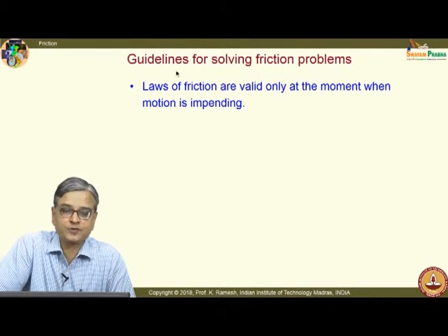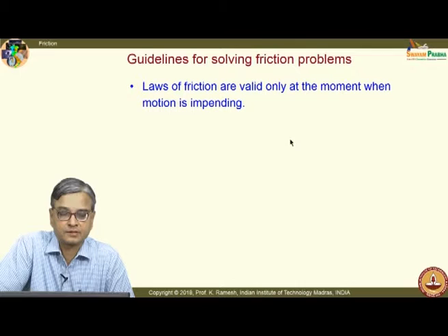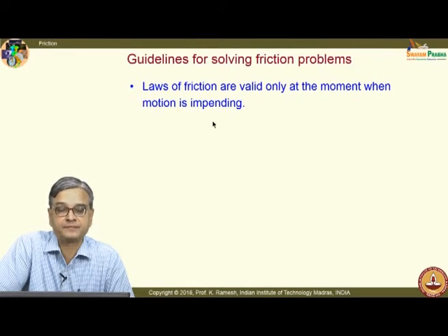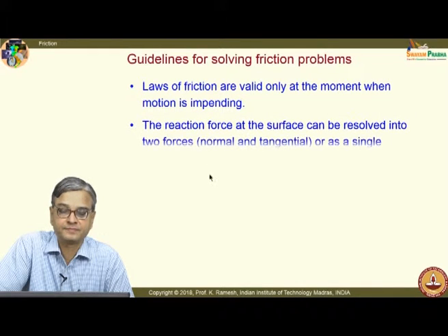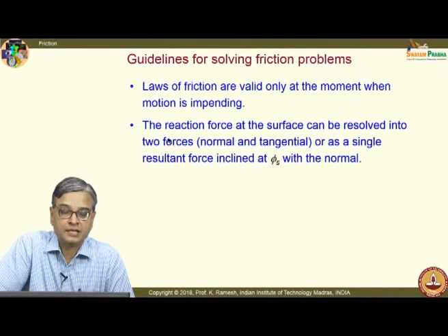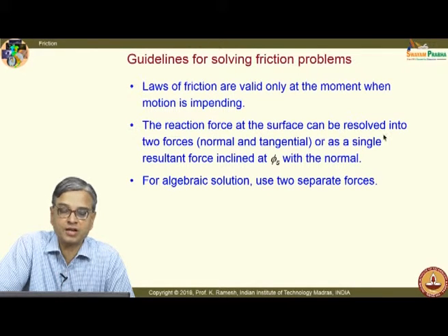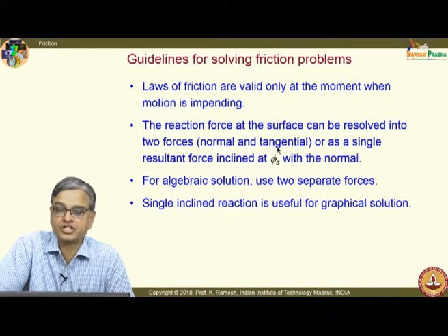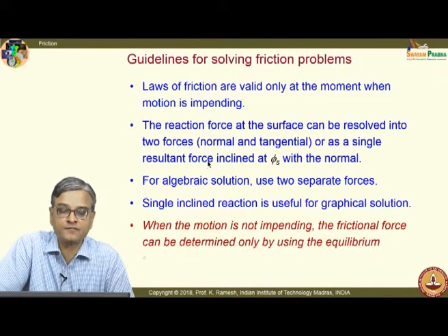So, what are the guidelines for solving friction problems? As I mentioned to you earlier, laws of friction are valid only at the moment when motion is impending. That needs to be investigated. The reaction force at the surface can be resolved into two forces, normal and tangential, or as a single resultant force inclined at the friction angle phi s with the normal. Whenever we use the algebraic solution, handling them as normal and tangential forces is easier.